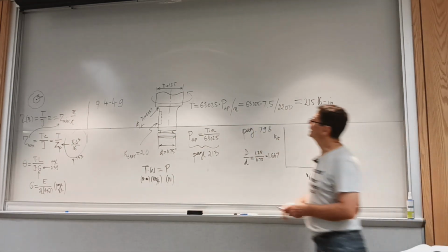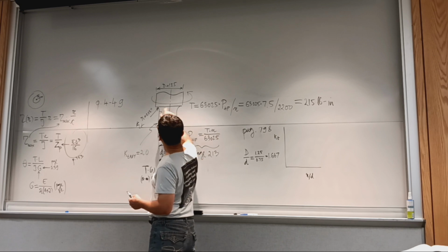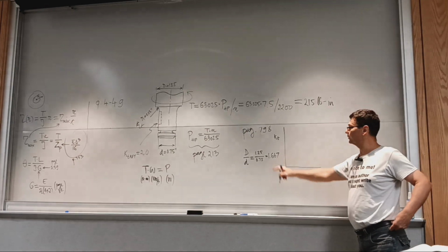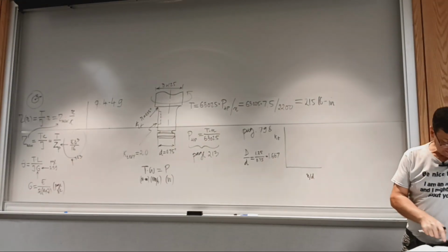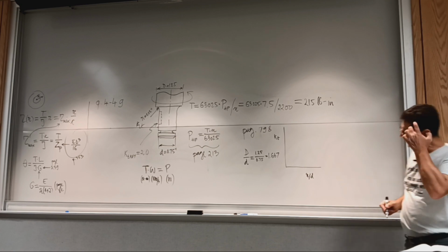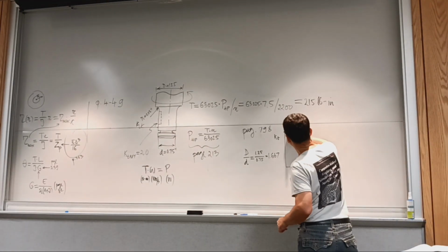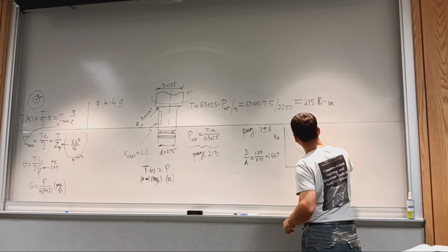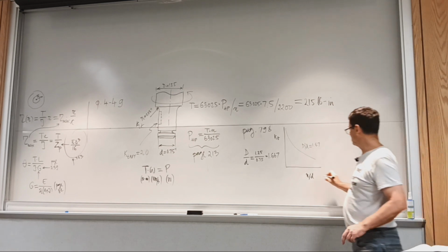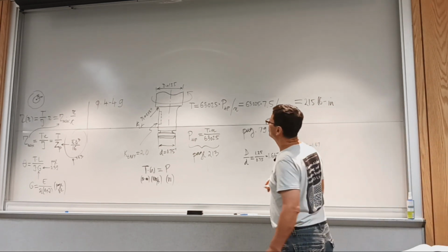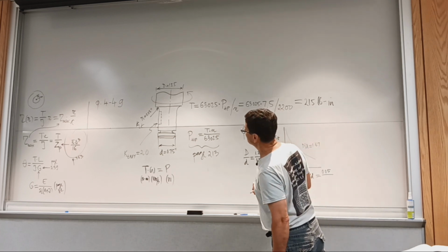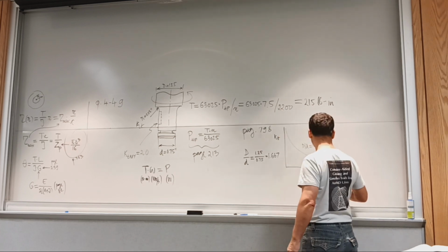It's a bit severe step. Usually want to have the difference less. The ratio between major diameter and minor diameter is 1.667, and it's a curve that is readily available. I think that was the reason why I chose it that way. So we have the curve that says D over d is 1.67, and then this ratio now is 0.05 over d. That's 0.75.